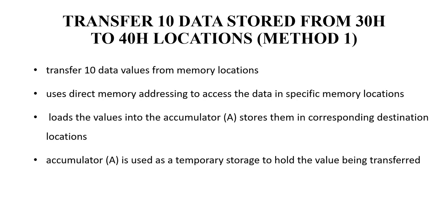Everyone. Today we will see a microcontroller program to transfer 10 data stored from 30H to 40H locations by using method 1. This program is designed to transfer 10 data values from memory locations starting at 30H to memory locations starting at 40H. And it does this by copying each byte individually from the source locations 30H to 39H to the corresponding destination